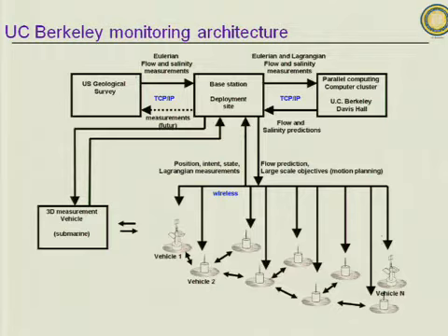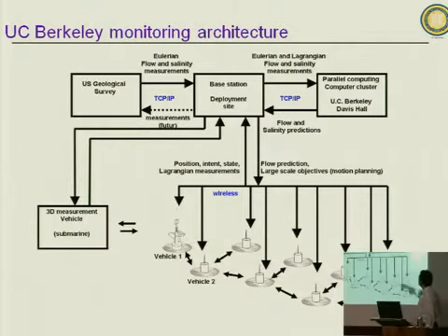So the vision here is very similar to the one I showed for the highway, in that what we're trying to do is develop a set of floating sensors, which are all linked wirelessly, also through a GSM module, through a base station on the deployment site, or now virtually here at Berkeley, and in which we can use power computing to do inverse modeling and predict the current in real time.